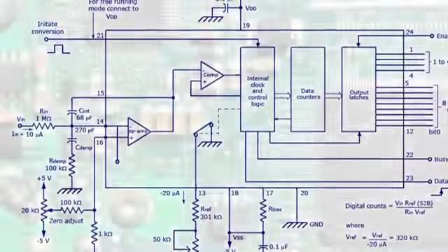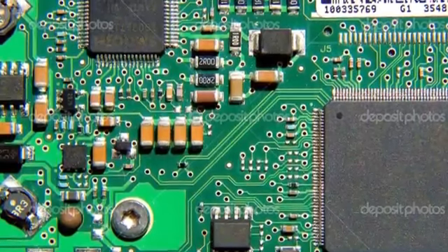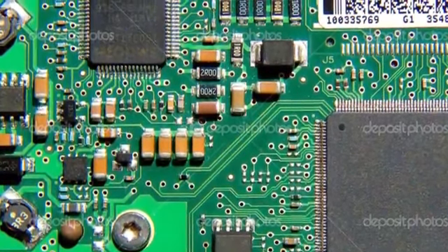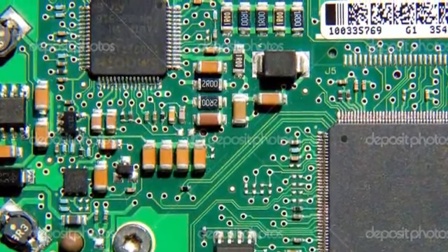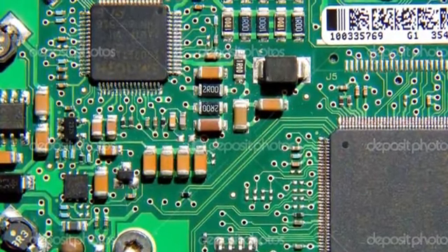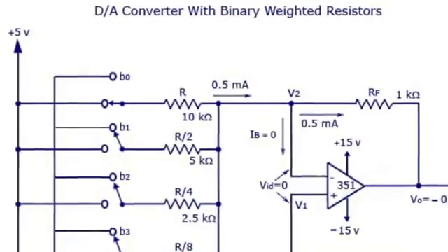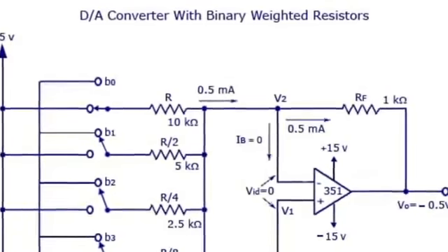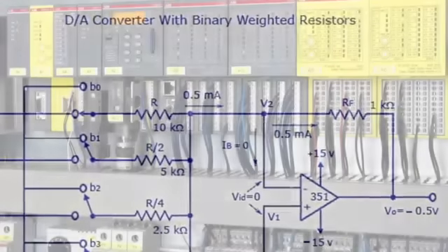Digital signal processing occurs inside the transmitter's electronics to adjust the signal for ambient and process temperature conditions, sensor response errors, signal filtering, user settings, sensor calibration, and a process variable display, to provide just a few examples. The resulting conditioned and processed signal is converted back to the analog domain to retransmit the 4 to 20 milliamp signal over the hardwired connection to the safety PLC.